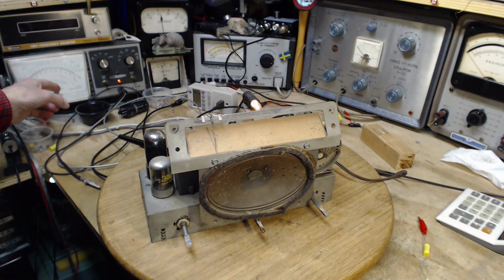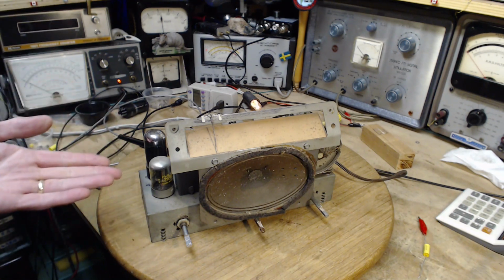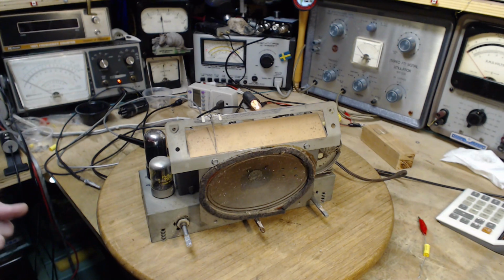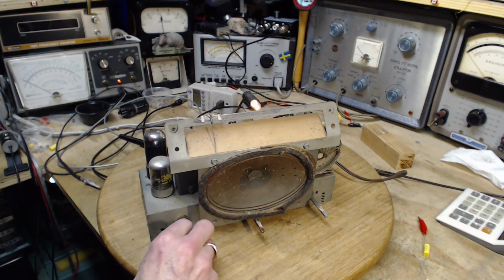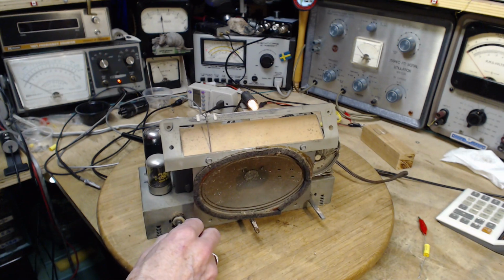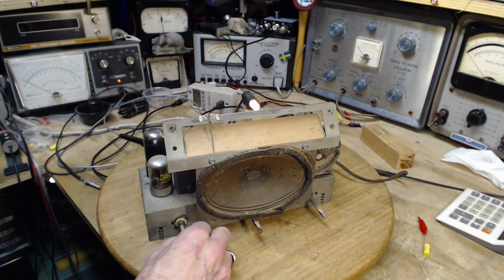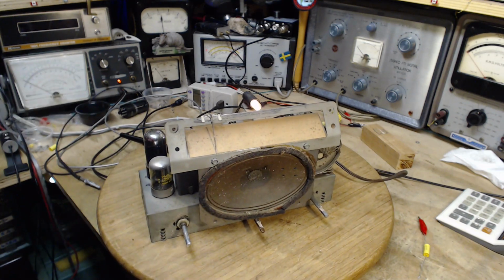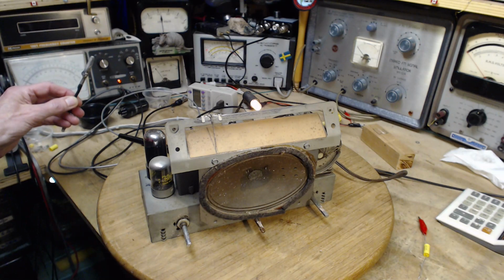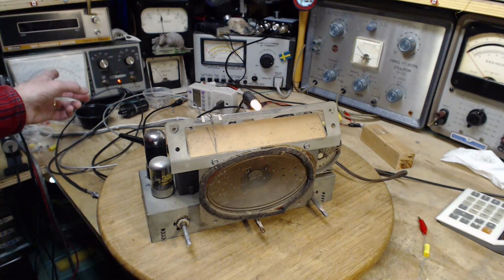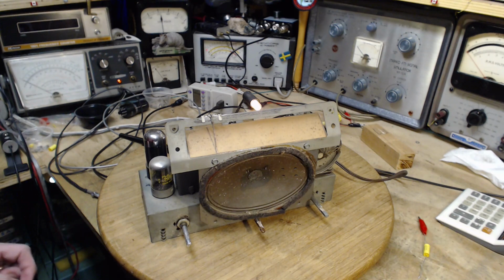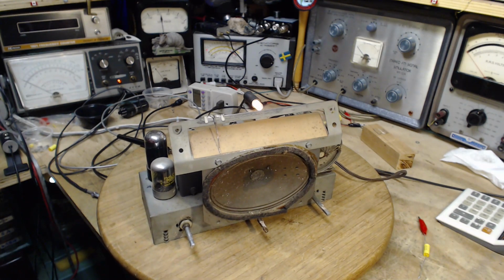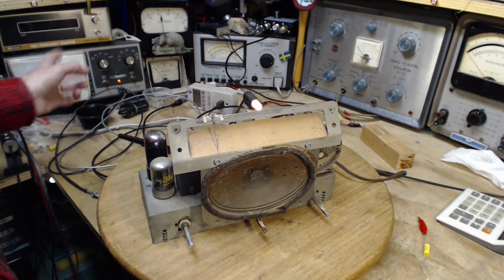So this should come upscale a little bit if there's a signal being processed by the radio, and that would include a little bit of noise. So this did come up a tiny amount. Wow, okay, that's a little bit of a strong hum there, but we won't worry about it. It's probably from the way I've got the equipment connected, because I have not connected the negative return on the meter here, because I'm thinking it's good enough to have the general ground in place on the radio, if that makes sense to you, on the B minus. We'll see what happens here.